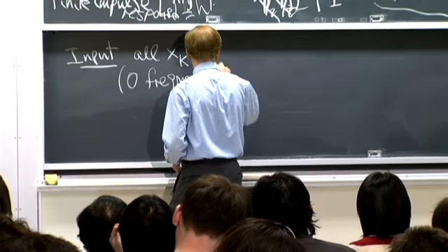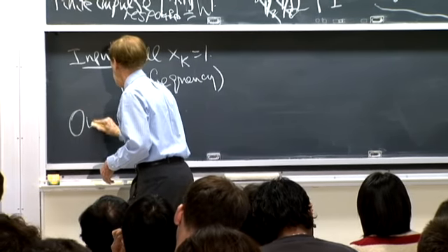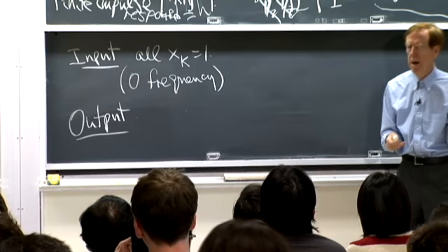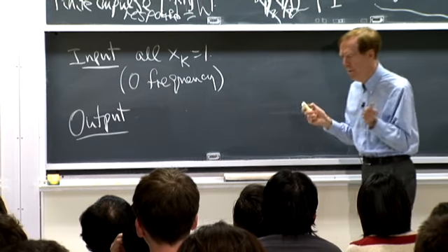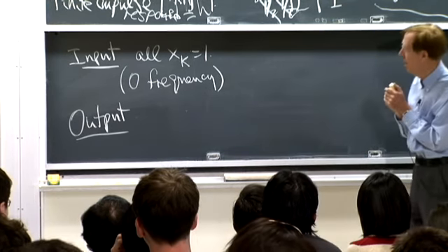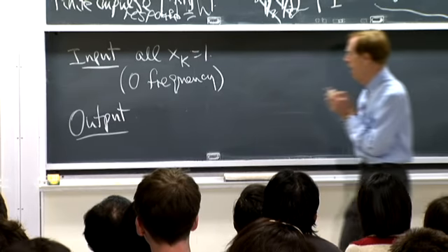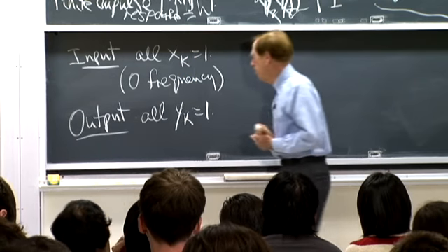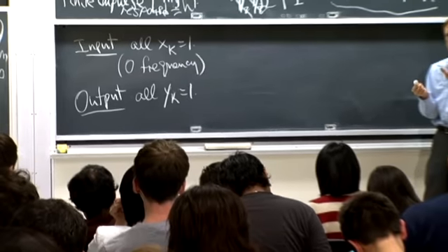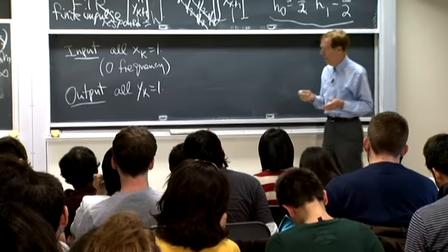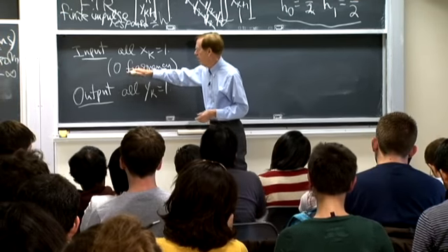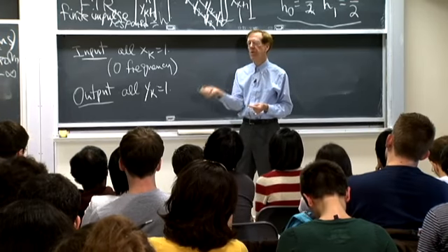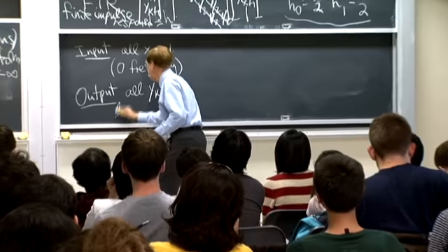What's the output from all ones going in? Well, sorry to ask you such a trivial question, you came in for some good math here, and I'm just taking a half and a half. So the output is all y's equal 1, right? So to me, that's telling, just to introduce an appropriate word, that low frequencies, in fact, bottom frequency, zero frequency, is passed straight through. That's a low-pass filter. That's telling me I have a low-pass filter.